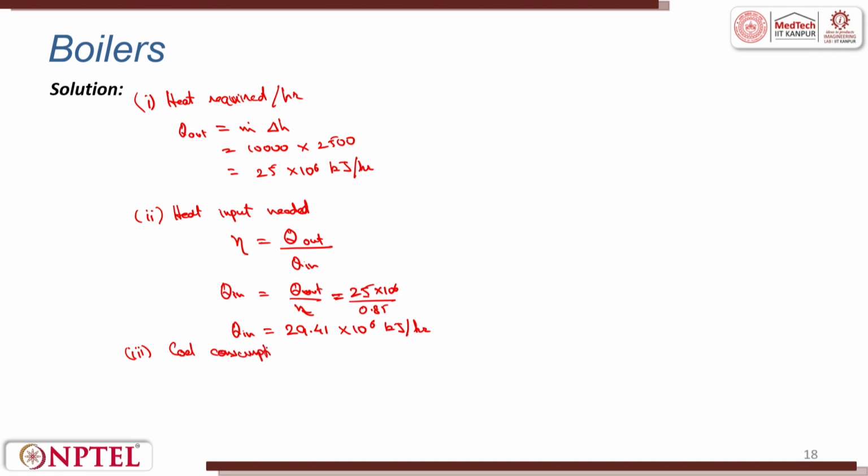Coal consumption, that is mass of coal required, is equal to heat input per unit calorific value of coal, which is also given in the question.